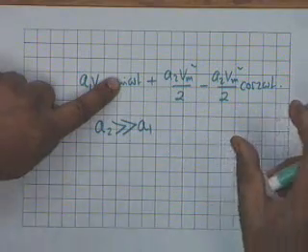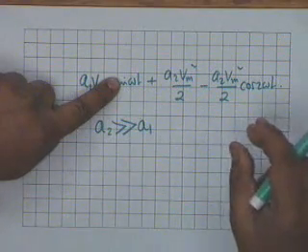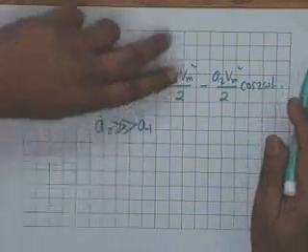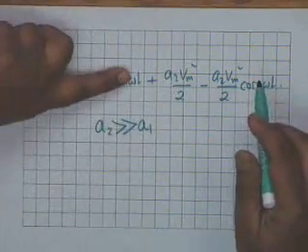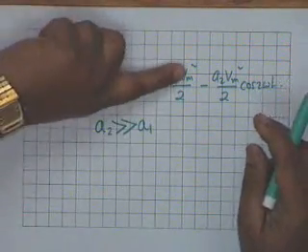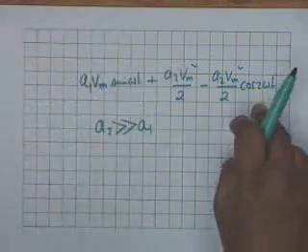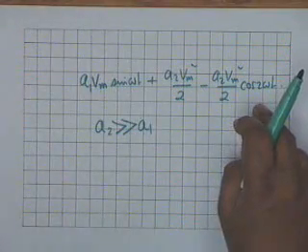If I put a capacitor in this circuit, it will not allow a DC to pass. So the current would be simply, this is negligible, this is blocked by a capacitor, so the current would be simply of frequency twice omega. In other words, the diode then acts as a harmonic generator.